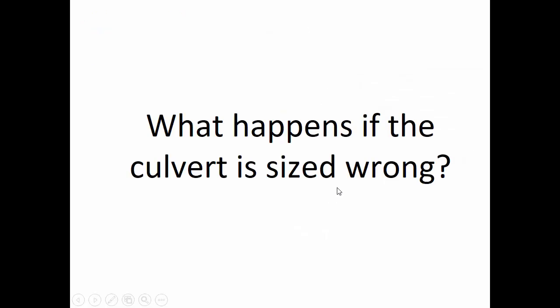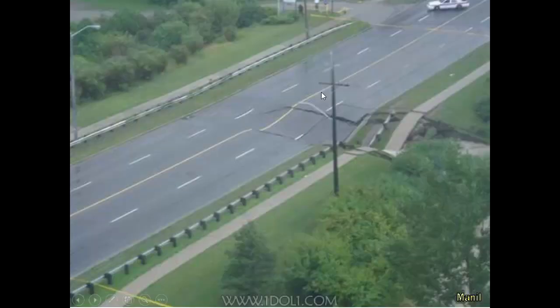And it's high stakes sizing a culvert, because if you don't have enough capacity in the culvert, then the end result is that flooding can occur. Now this is a series of photos that was taken. The water flows from up here through a culvert and into a creek downstream of the culvert. And there's a culvert that goes under this road, and you can already tell that something's gone wrong. And what went wrong was the culvert was too small, and the water level got high upstream.